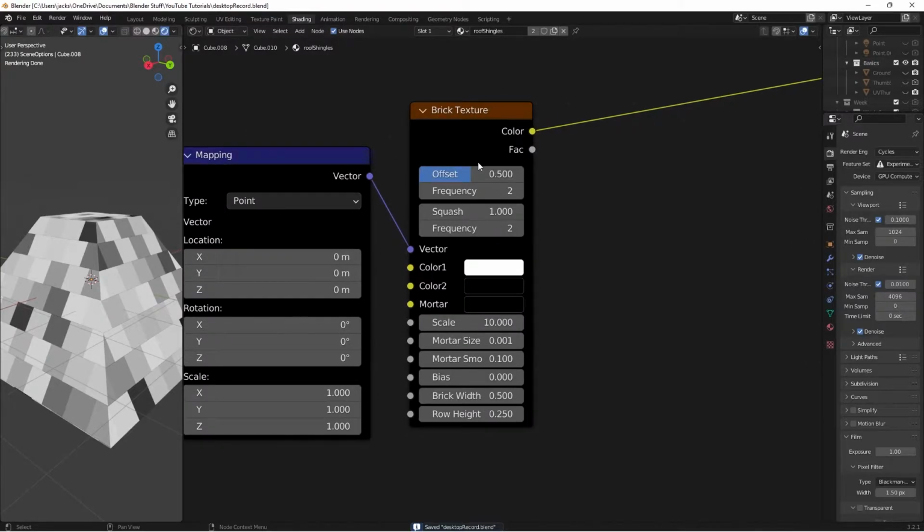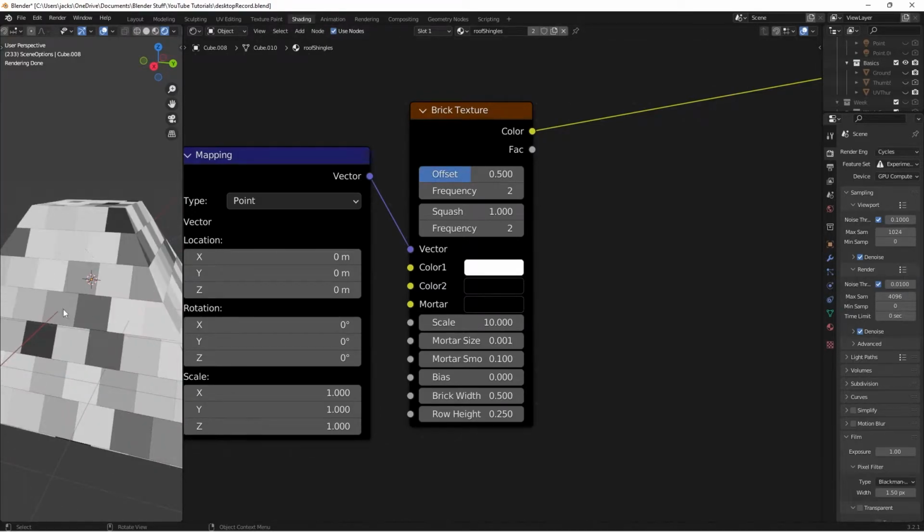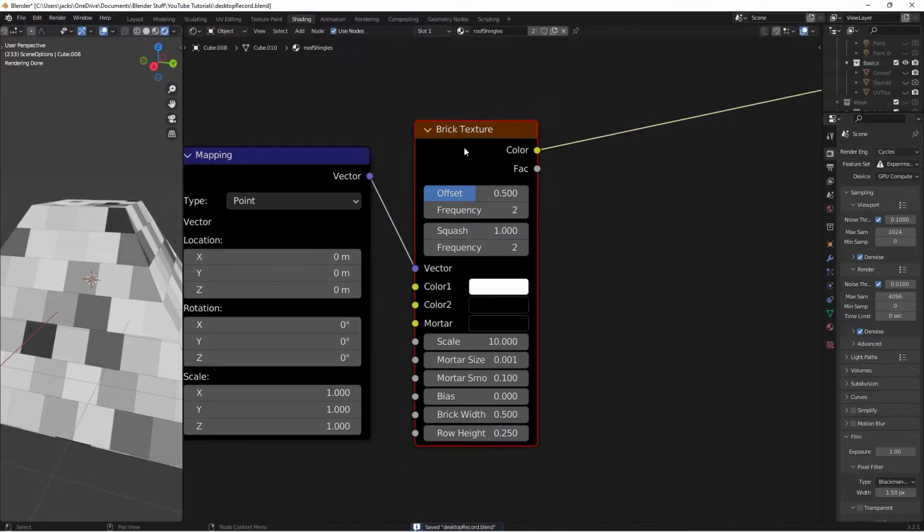Then I'm going to change this offset here to a 0. If you want everything to be lined up perfectly, use 0 offset. If you want it to be sort of staggered like this, then you leave it at half. Depends on what you're going for. I'll actually leave it at half because I kind of like that better, but some roofs have it to where they're all perfectly lined up sort of, and they're not overlapping as much. But yeah, you can also make them brick style if you want, instead of being squares like this, by simply moving this up to like a 1.